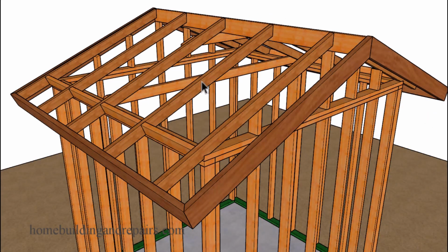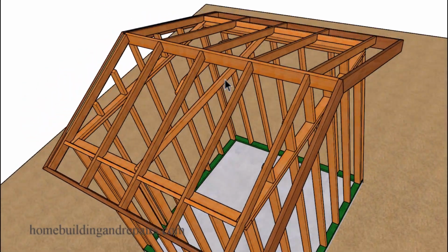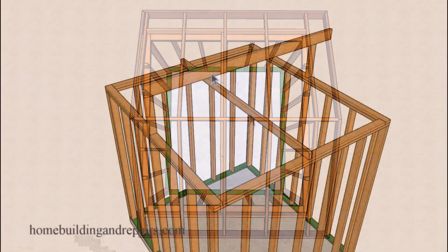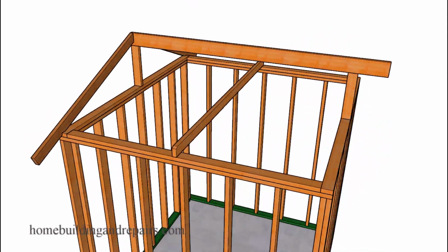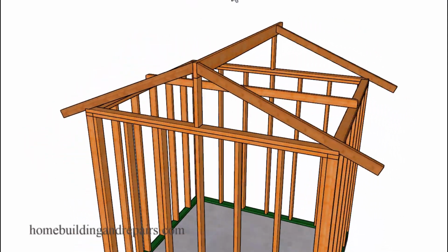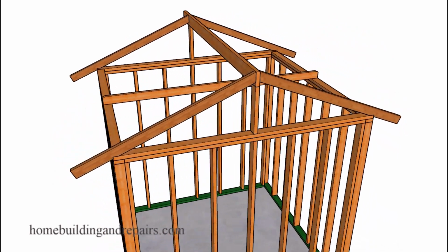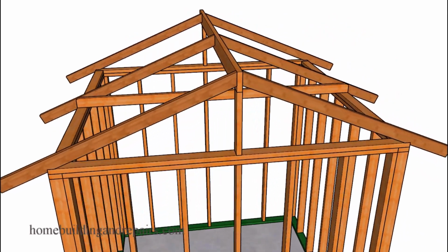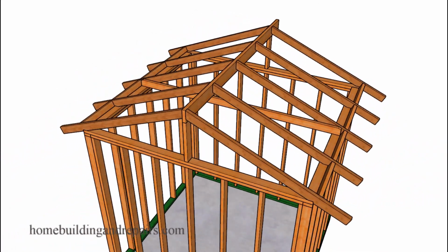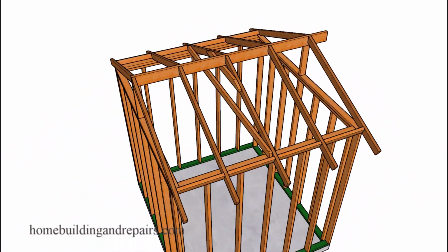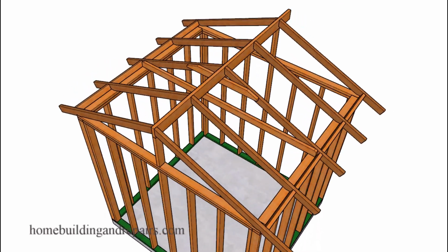However, for someone like myself, this is a no-brainer, because if all of the components were cut for both types of roofs, I could probably assemble the conventionally framed roof in about the time it would take somebody just to build the roof trusses. And if I was using the correct lumber sizes, I wouldn't have to worry about the trusses being built incorrectly or with the wrong building hardware or connectors that could end up failing over time.